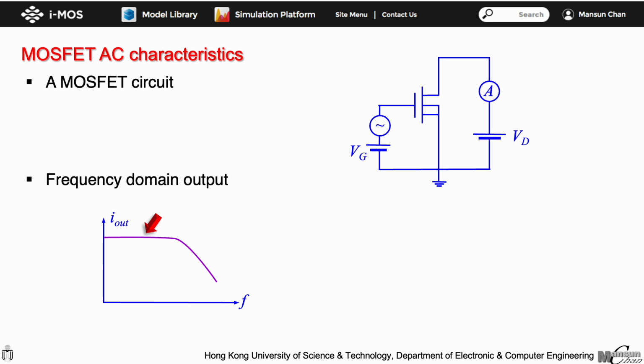The MOSFET initially provides a high AC current gain. When the frequency increases and becomes so fast, the output current cannot follow the input, and the gain or magnitude of the output current variations will drop. However, many earlier models failed to predict this simple behavior. The typical level 1 model produces a flat frequency response curve as shown in the given figure.